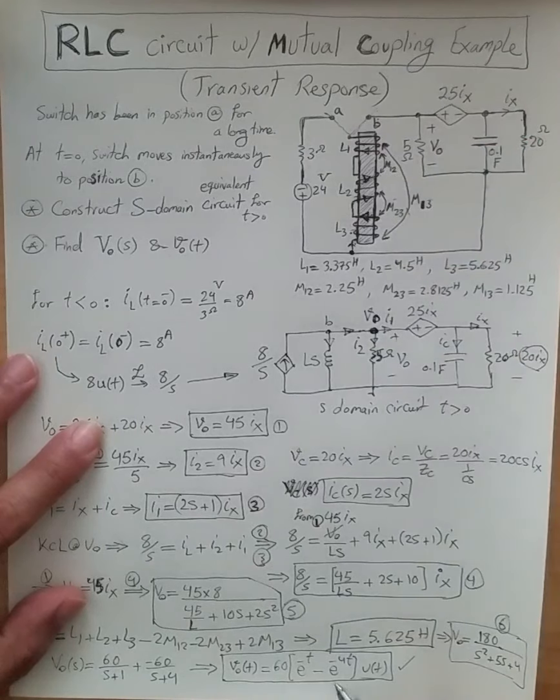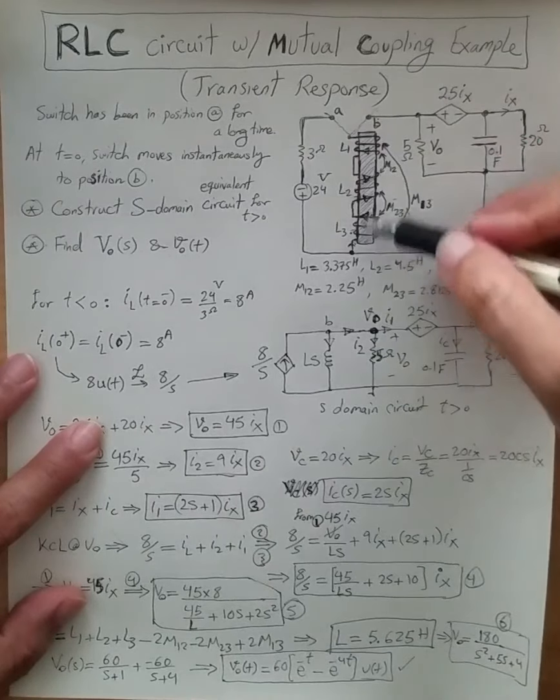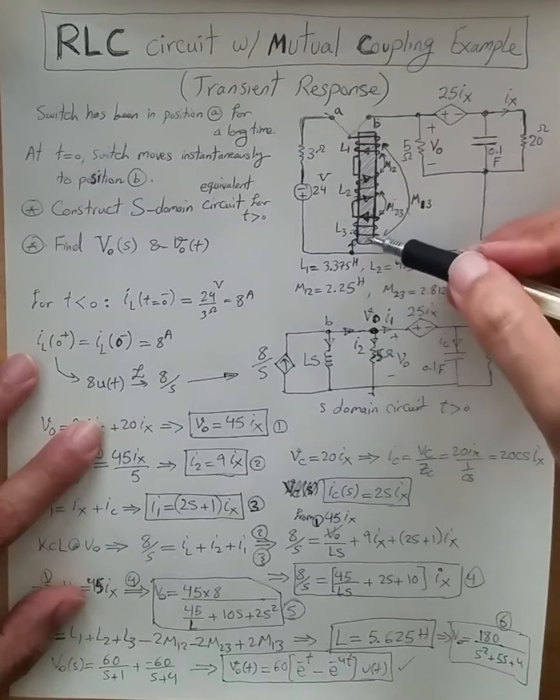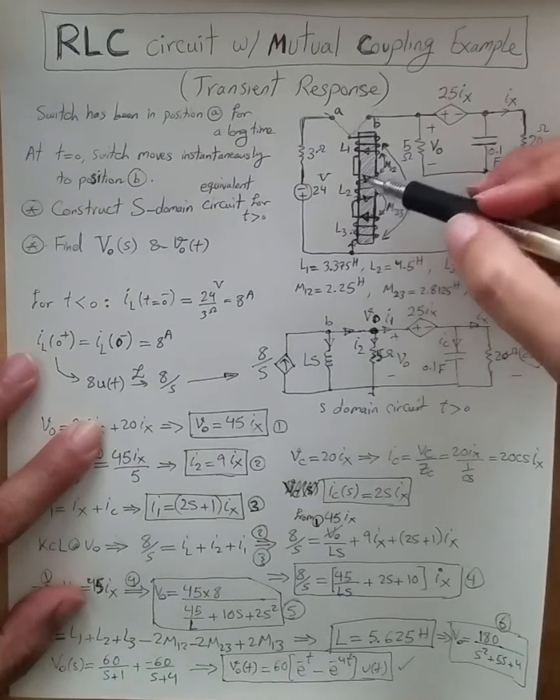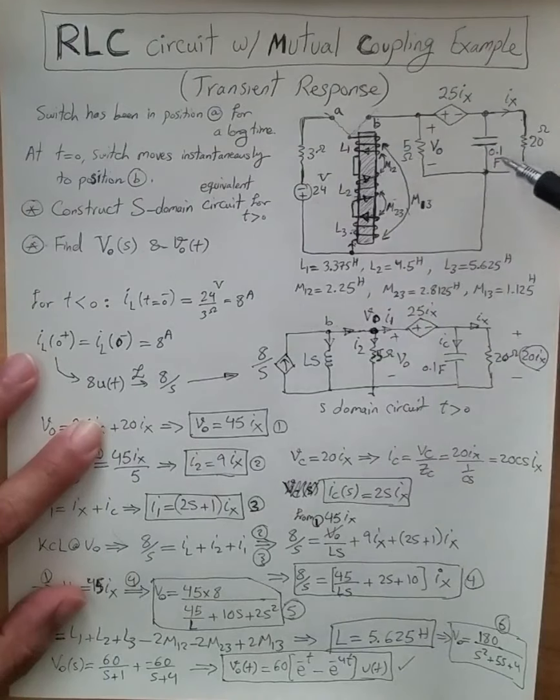And then at time infinity, the whole current is consumed, the whole magnetic energy that was saved inside the inductor is already wasted through the circuit, through thermal dissipation. So that's why we expect that at time infinity the voltage has to be equal to 0, which you can see, because at infinity these two components become 0, so voltage becomes 0.